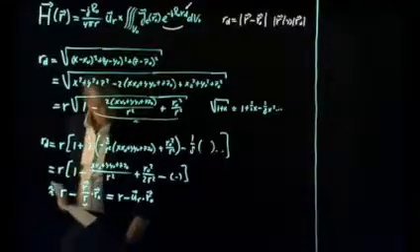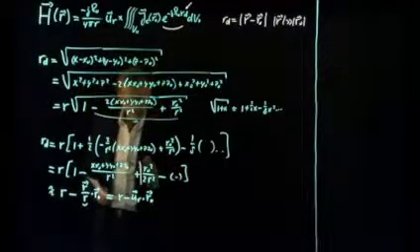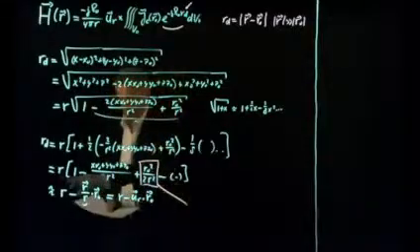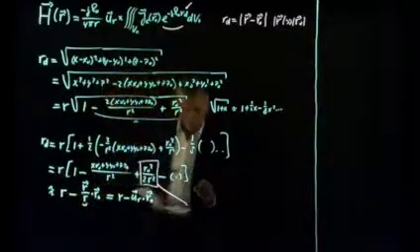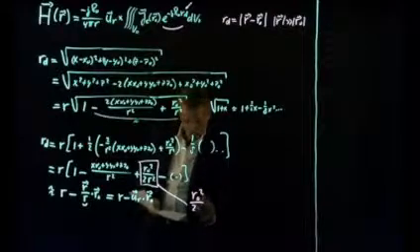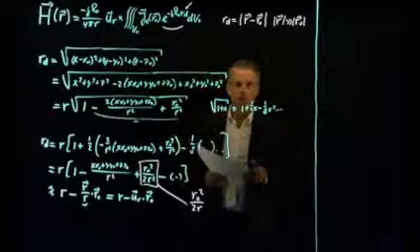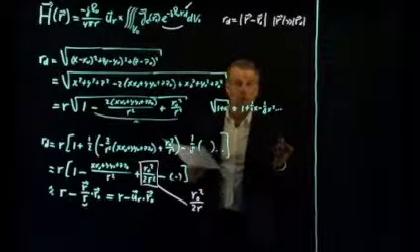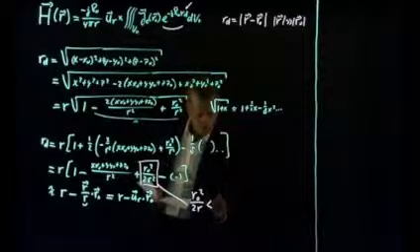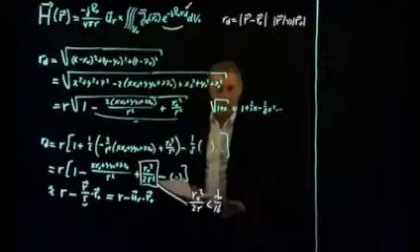And this approximation holds when this term here is small enough, and that means that this term, don't forget about this R, R naught squared divided by 2R should be small enough. And in the past, people in the antenna community decided that small enough means lambda naught over 16. So it should be smaller than lambda naught over 16. And what does it mean?